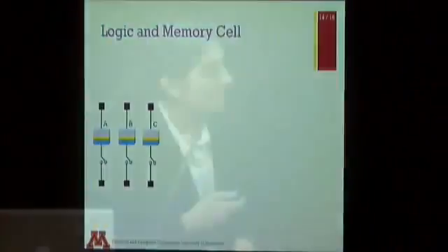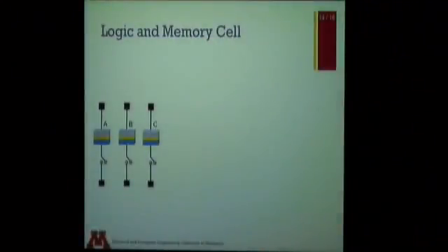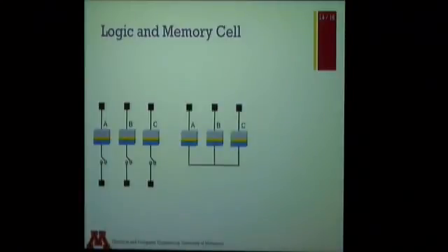So this particular structure here is this very classic 1 MTJ, 1 switch circuit in the memory. So this is the single MTJ, single switch, or single transistor circuit replicated 3 times. And that has a very nice regular structure to it, a very nice memory array-like structure to it. The logic structure that we just saw was this particular structure, and even that has a very nice regular feel to it.